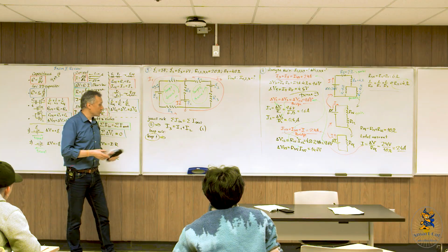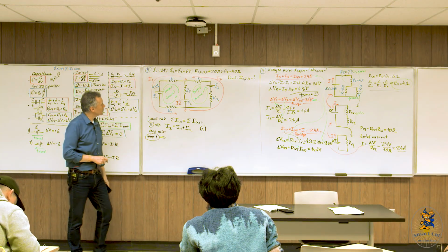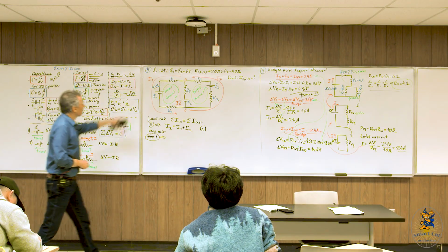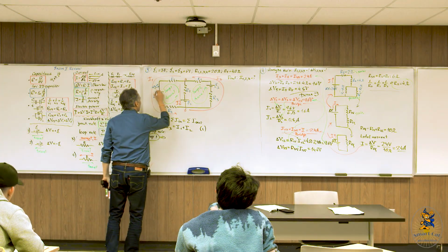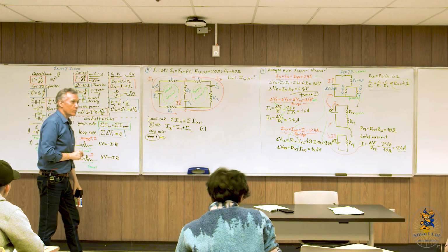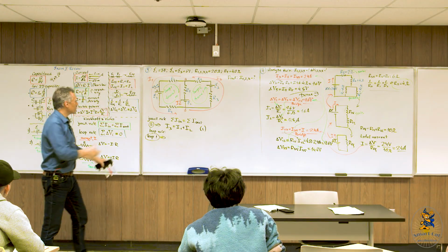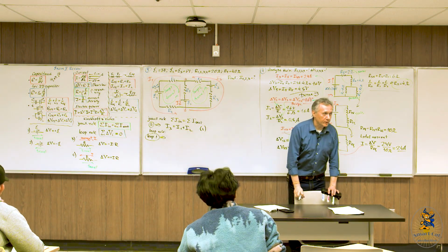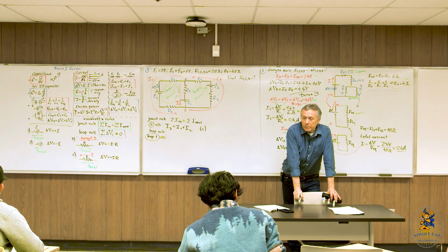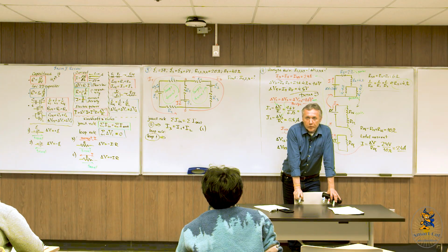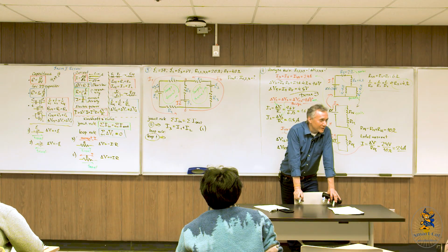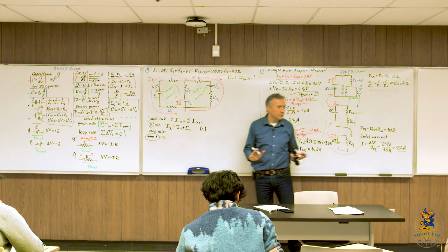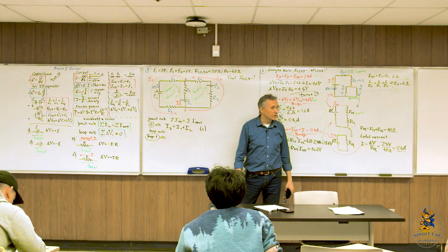What's the contribution to the loop equation from the battery? We're traveling this way, so this is plus, this is minus. We're traveling from plus to minus. When you analyze the battery, you need to remember we need to know only the travel direction. It doesn't care about current direction. It's a common mistake. I remember several years ago, a very strong student got confused at this particular point. So the travel direction we need to know to analyze the battery. As a result, contribution?